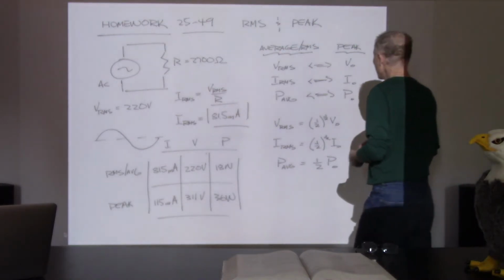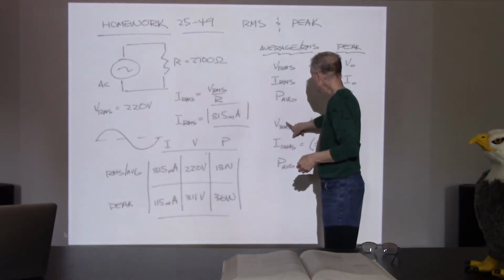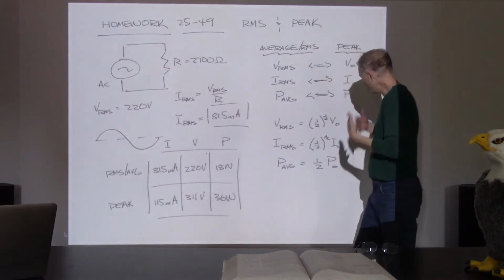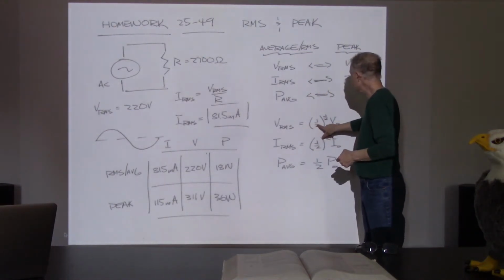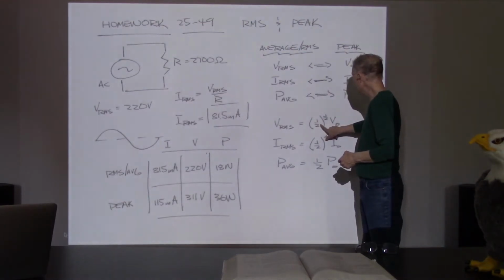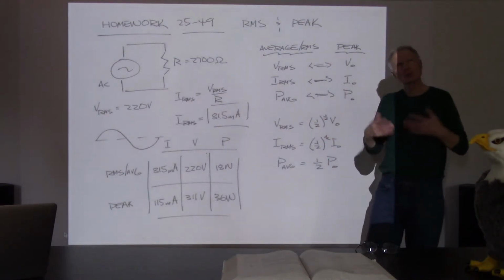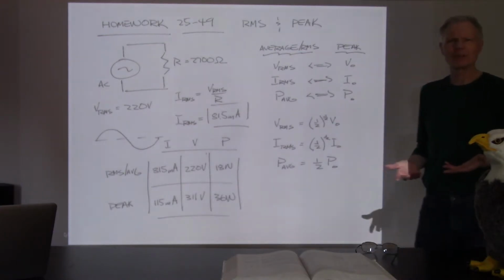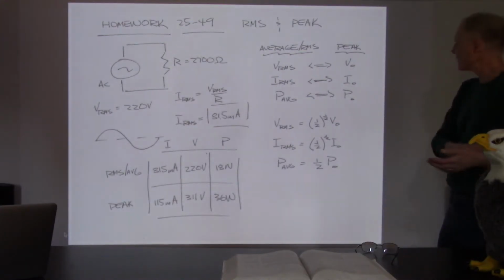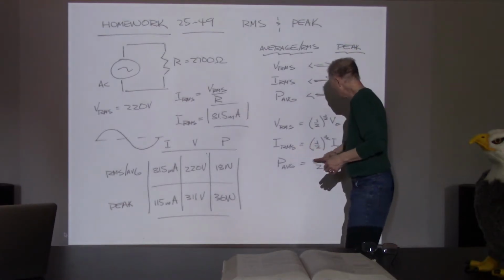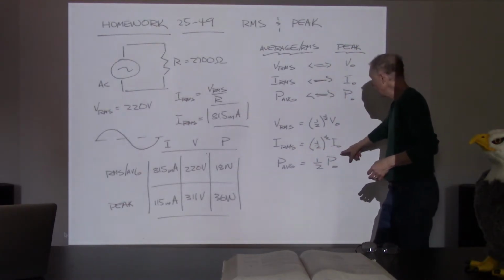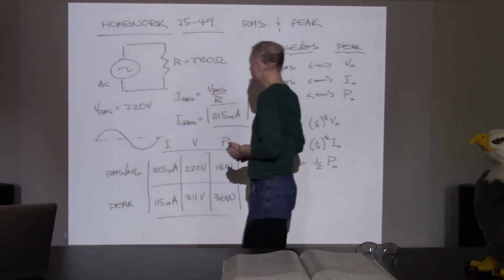And so for that, we can do a root mean square averaging. For a sine or a cosine function, the root mean square value is the square root of 1/2 times the peak voltage, which works out to be about 71%, 70.7, something like that. For the average power, that's going to work out to 1/2 of the peak. So let's see what they gave us in the problem.